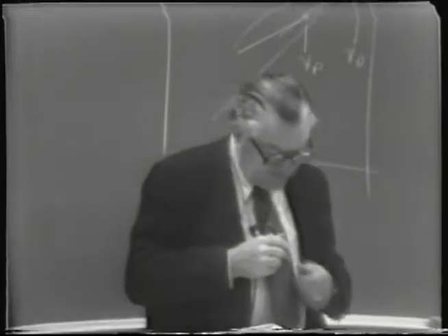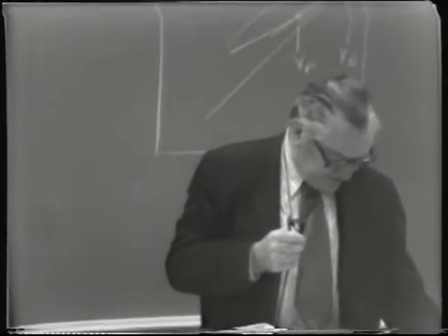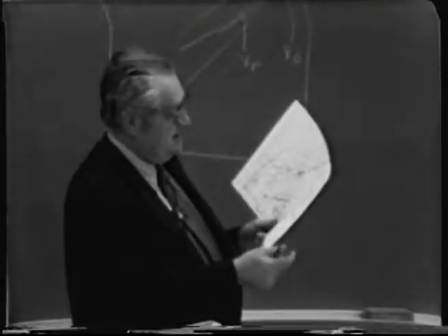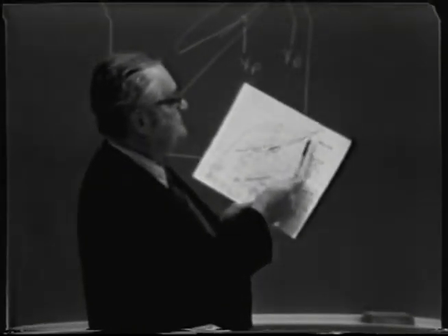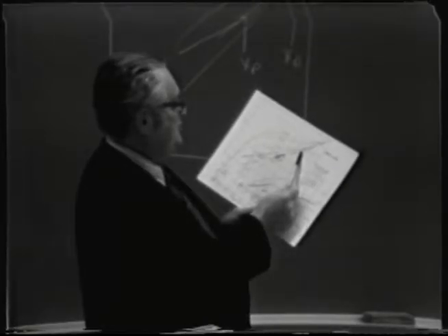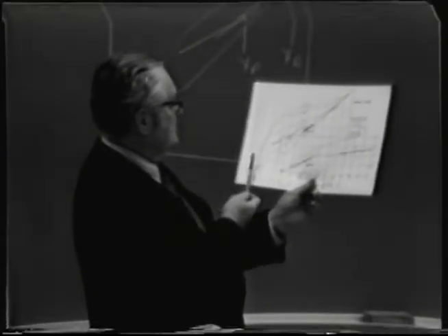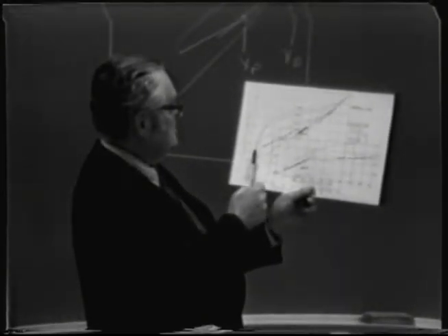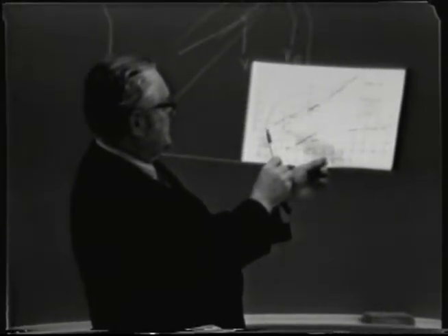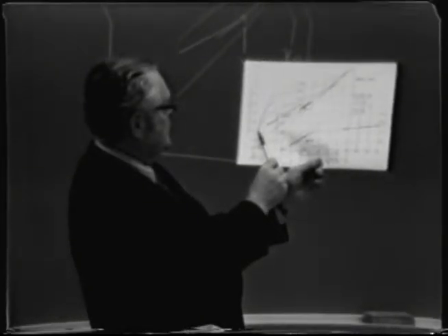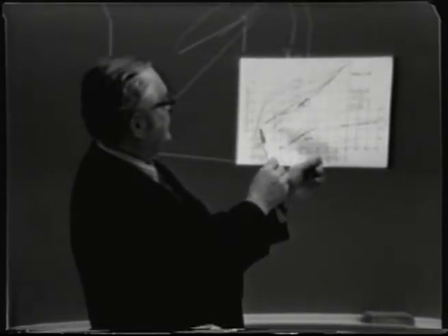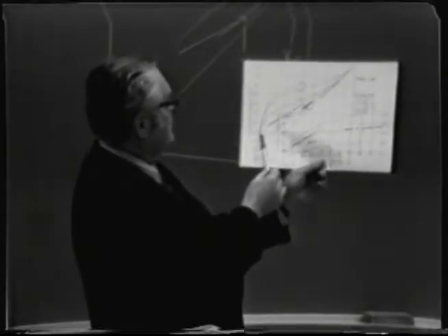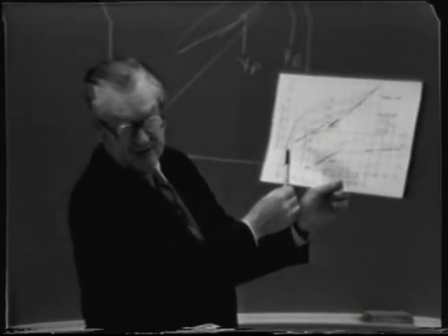All right, what's the minimum reflux ratio? Well, now we have to go back to the chart for that. And you'll see that we've drawn in a dotted line here, which, because the feed is at such low concentration, the minimum reflux ratio is determined by the minimum slope of that line, which would satisfy the requirement of extending the operating line clear down to the intersection with the Q line.